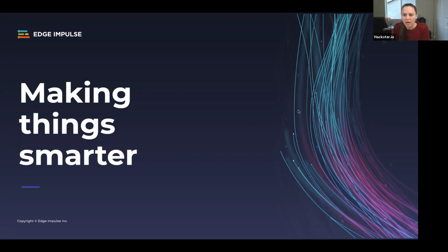Great, thank you. Let's see, another one. What kind of range can you get from a sub 1 gigahertz board? Yeah, it often depends on exactly how much data you're trying to send through. But you can easily get in the hundreds of meters range with very low transmit power. That's the other variable: as you go up in transmit power, you're consuming more power, but you're getting more range out of it. So it can be tuned based on the application. And if you go to those TI resources, they'll have the trade-off curve of how much power you need to transmit to a certain range under what conditions.